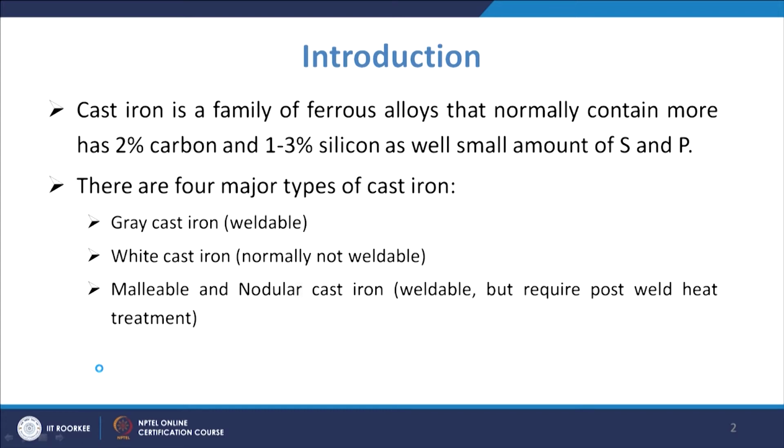Then you have the malleable cast iron and the nodular cast iron. Malleable and nodular cast iron are weldable, but they require post weld heat treatment.